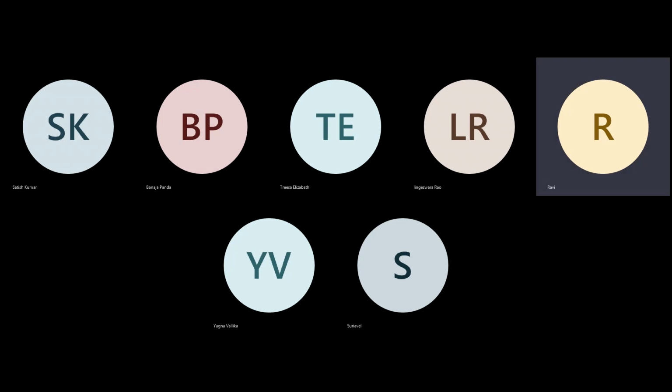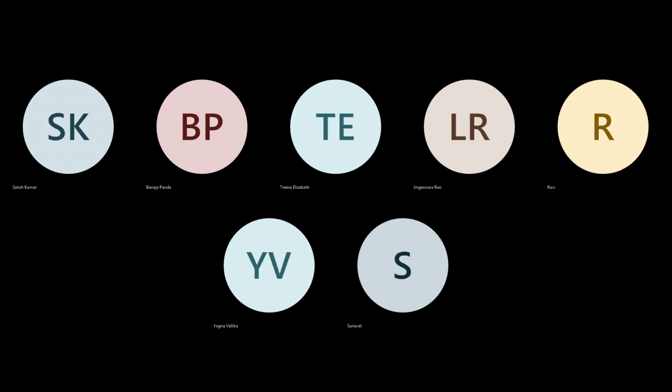Where it will try to optimize and look at that, then comes, okay, I've placed it wherever possible. Now I have to actually go and do buffering, or we will talk about those steps. But the importance of coarse placement is like this: net length is the first priority. Second, after net length, is to match the criteria you have set. In case you have put upfront a criteria of, for example, macro placement, then the first thing it will try to do is place all the cells closer to the pins, because that's your first criteria. It will give that the highest priority.